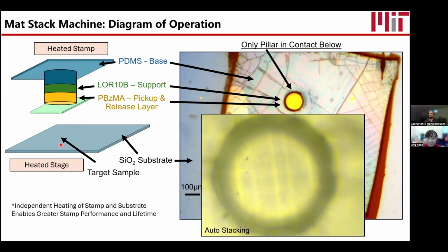They expand. However, the machine was fixed, so the polymer had nowhere to go and it shifted. We have tons of movies trying to figure out what's going on and how we can resolve it. Ever since we've added this heated stamp, there seems to be no movement, and I believe it's a huge increase in performance. So the heated stamp and keeping things the same has improved from that aspect.